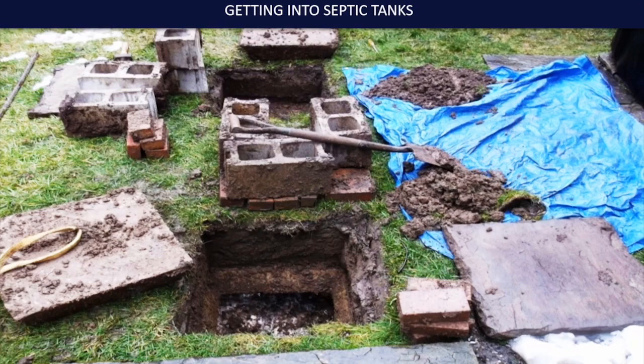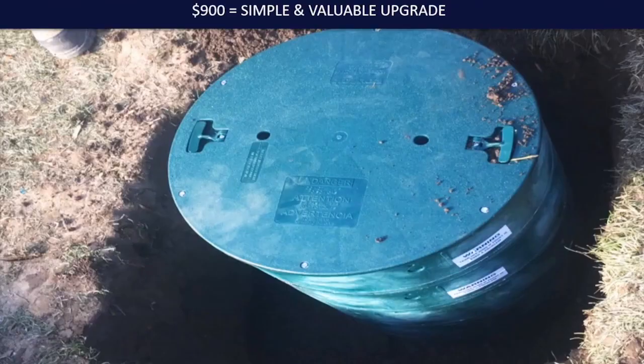This system had failed, and the water was coming out the lids, so they put the cinder blocks on the lids to hold the lids down and hope that it would force the water into the right spot, when we could just do this. So if you have a standard septic tank and it has 2 lids and it's 3 feet below grade, it'd be about $900, materials and labor, to put these types of lids on to bring it permanent access to grade and sealed.